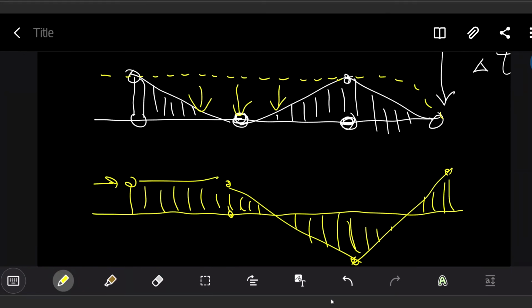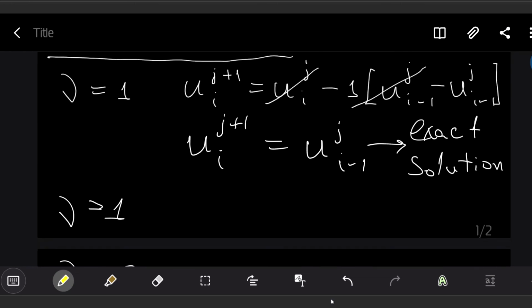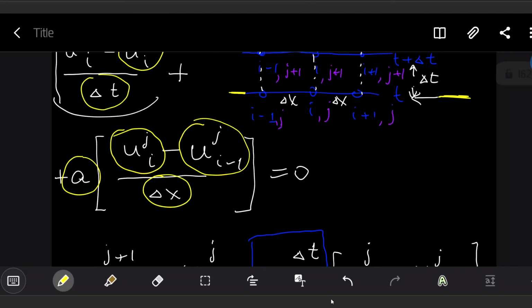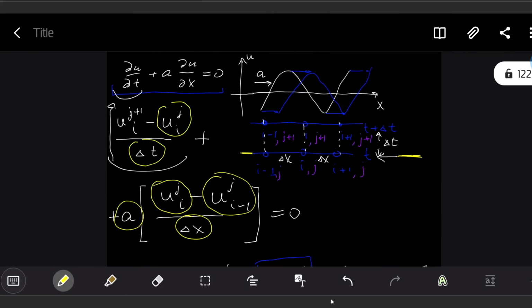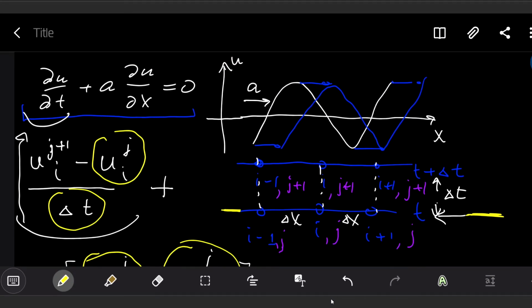So your question may be the following. In Fluent, we can simulate with Courant number 2, 3, 5, 10, 50. And there is no problem. Yes, there is no problem. Because the way of transformation of the initial equation in derivatives is different from what I wrote you here.